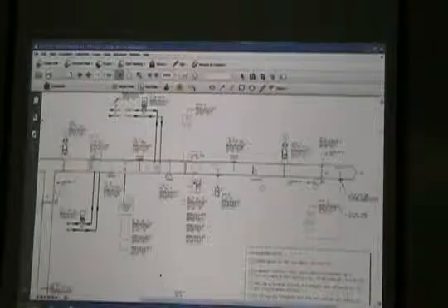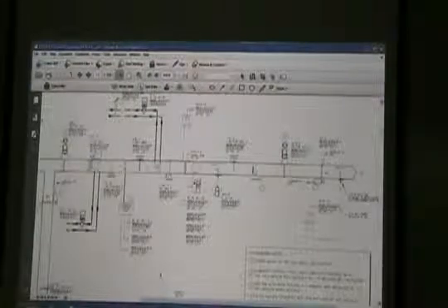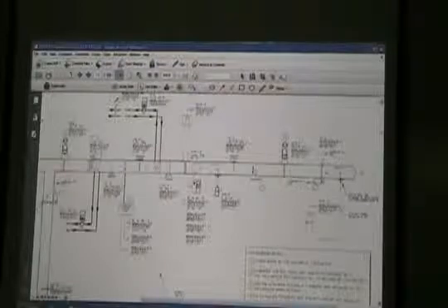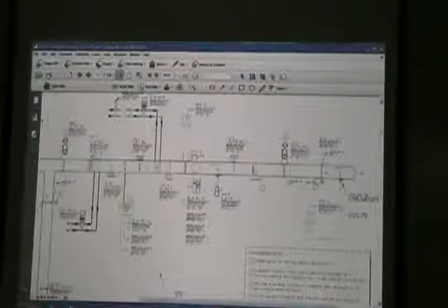In a hospital, we have a lot of patient rooms. They're all designed for 6 air changes. That's about 1 CFM per square foot. If you were involved in some of the earlier training, we determined that 1 CFM per square foot is about an average load in a space without a lot of glass. Interior spaces are about 0.7. Exterior spaces range from 1 CFM to maybe 2 CFM, depending on west exposure, east exposure, north exposure.